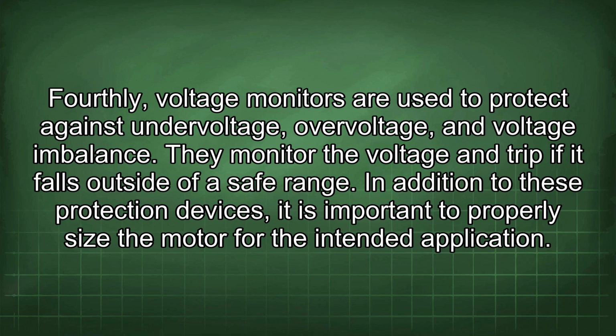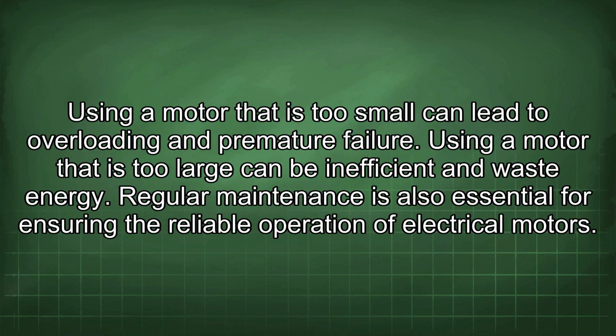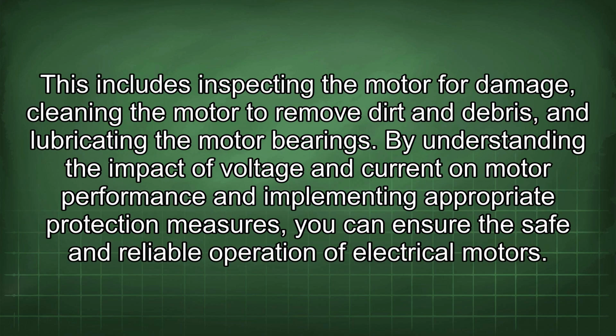In addition to these protection devices, it is important to properly size the motor for the intended application. Using a motor that is too small can lead to overloading and premature failure. Using a motor that is too large can be inefficient and waste energy. Regular maintenance is also essential for ensuring the reliable operation of electrical motors. This includes inspecting the motor for damage, cleaning the motor to remove dirt and debris, and lubricating the motor bearings.